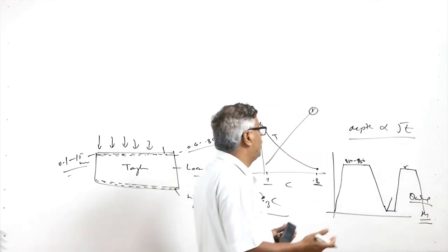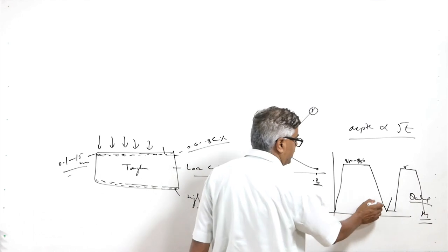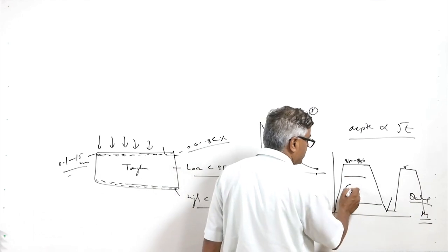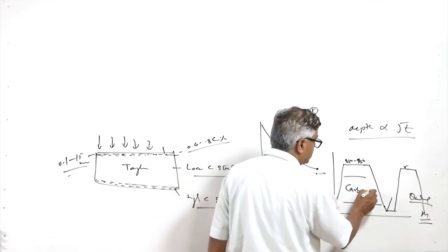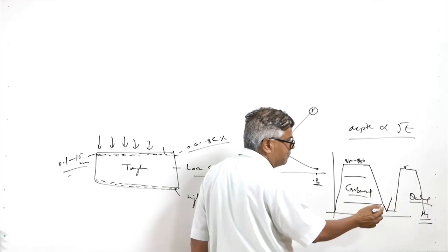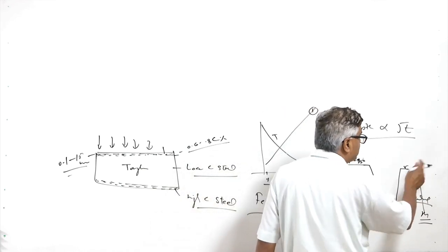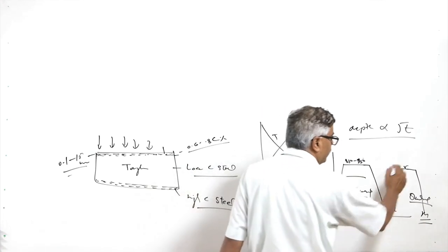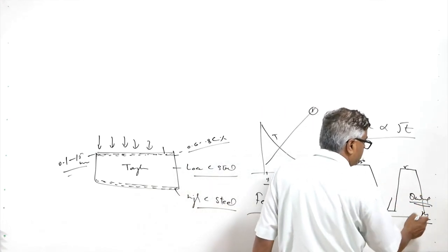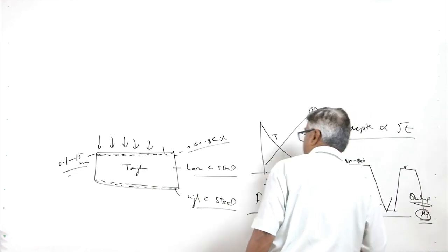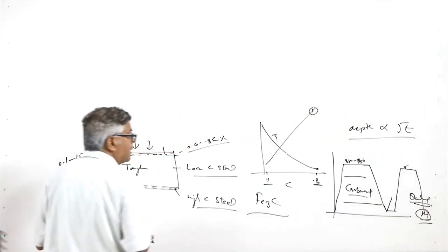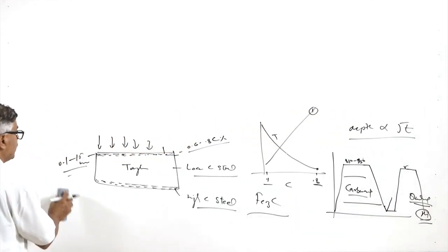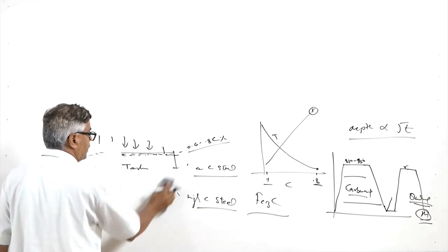So basically the objective is, first heating and holding is done for carburizing purpose, and once this is over, carbon enrichment has taken place. Thereafter again it is heated, so that homogeneous austenitic state is achieved, followed by the rapid cooling or the quenching, so that hard martensite is formed. This is the kind of heat treatment cycle which is used for the purpose of the carburizing.